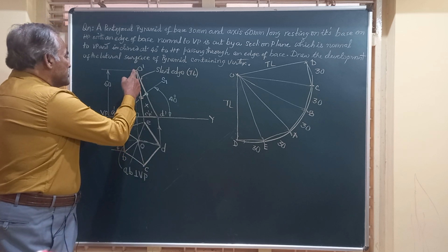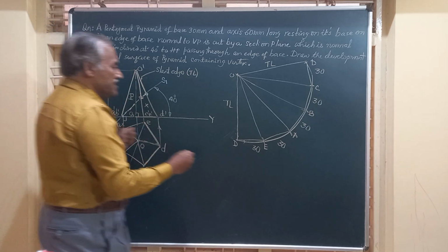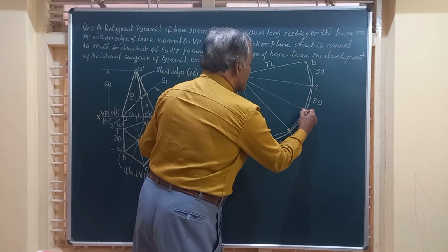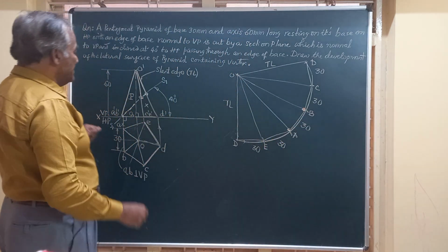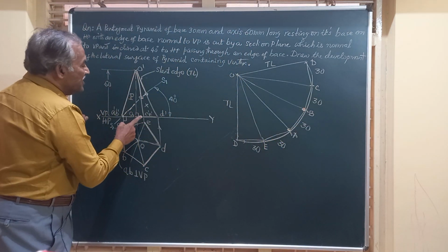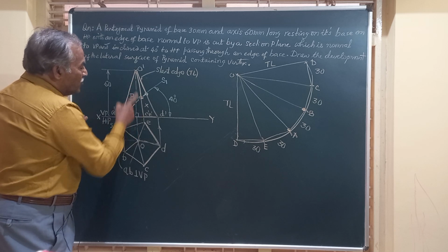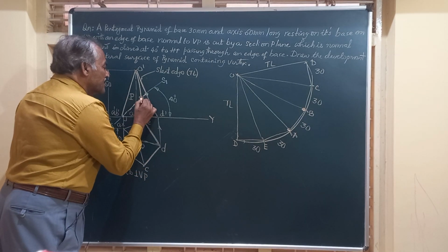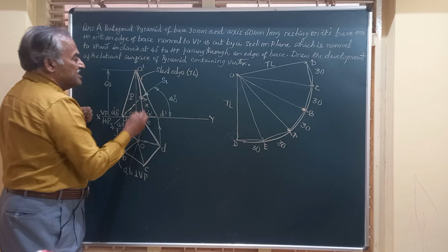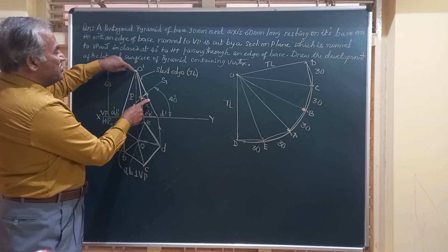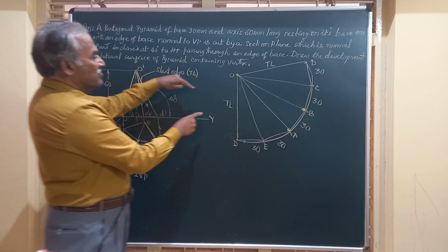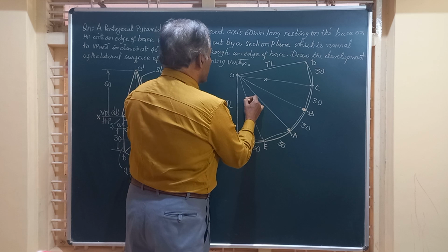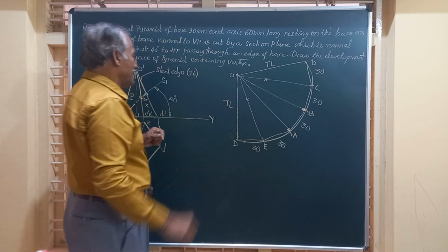So here, the section plane is passing through A and B. Friends, A is here, that is 1 point, B is here, so you get 2 points. Then friends, OC and OE are cut here, but OC and OE do not represent the true length. Hence, that point should be shifted to the last line, that is the true length line, and we take this measurement on OC and OE. On OC and on OE, we take equal measurement. So this gap is equal to this gap.